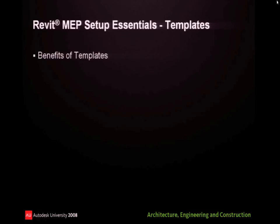Templates are a powerful tool that should be looked at hard up front in your project setup. If you've been using Revit for a while and have not spent much time on your templates, you ought to go back and look at them. I've been hearing that in other MEP classes I've attended this week. They're going to give you a template for no charge with all the mechanical and electrical content in there, and I think that's going to be up on the AU website. Templates are very powerful because they give a project a head start and the same look and feel. They even allow some tasks to be done more efficiently, and they help you set some standard processes within your organization.